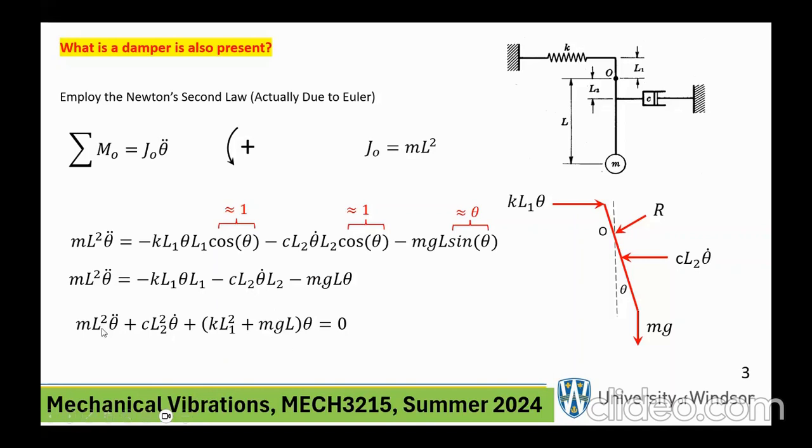So what you see here is the effective mass, effective damping constant, and this is the effective stiffness. The natural frequency is always the square root of K effective over M effective. So this is written here. The equation is then up there, and there it's repeated.